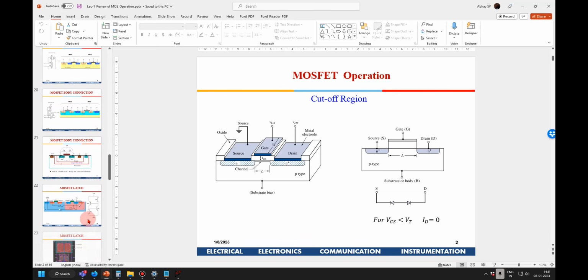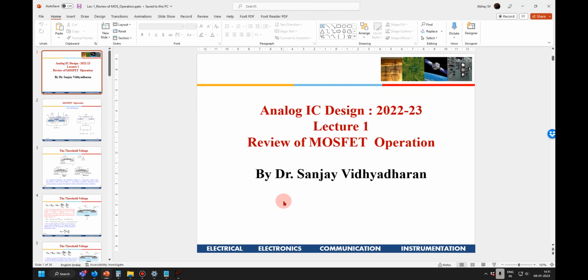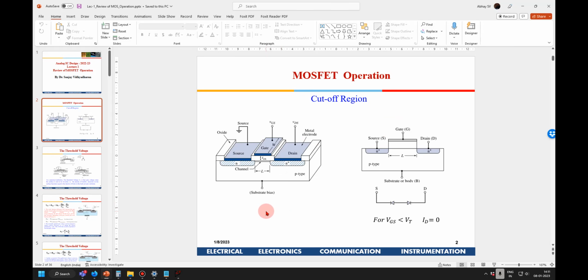Suppose you have an inverter. We saw the inverter has a PMOS on the top. Because of holes, the mobility of PMOS is slower. So while the output node is charged to high, the PMOS will charge it slowly, whereas the NMOS will discharge it faster. Is it understood? In that case, to compensate, I can have a PMOS twice the width of the NMOS.